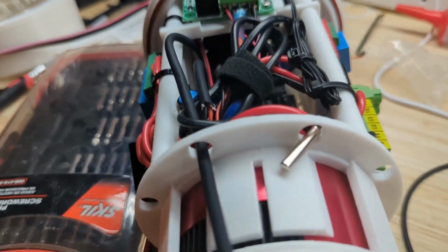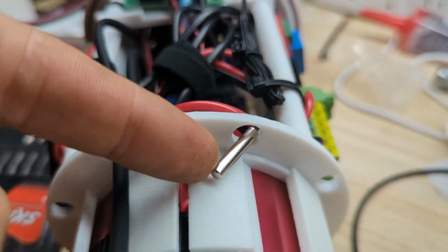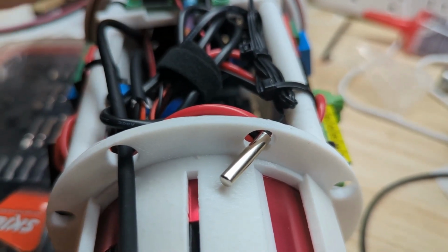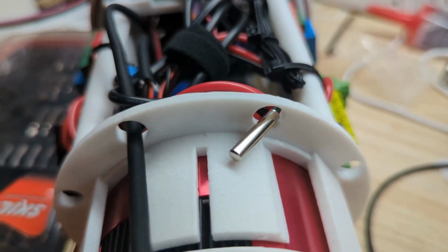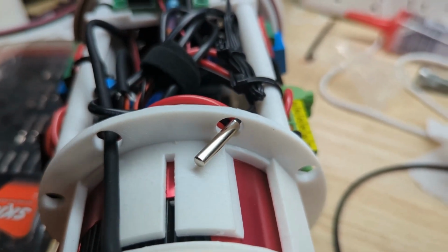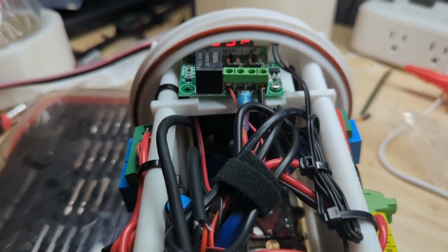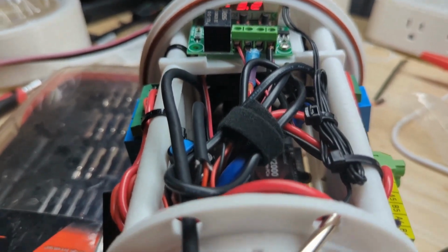And of course, where you put your thermostat sensor matters too. Obviously, you don't want to put it right next to the Pi, because if it's blowing its fan, it could put some hot air out too. Put it up into an area that's not going to be near where any other warm air could be circulating, so you don't get an on-off switch, like a false positive.